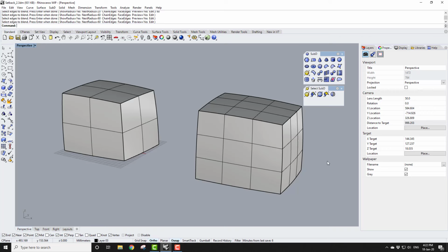However, iterating through and adjusting the results can be time consuming. Version 7 introduces an improvement in the Blend Edge command that allows for setback corners in difficult circumstances, as for example if I wanted 3 different nominal radii on these blended edges.